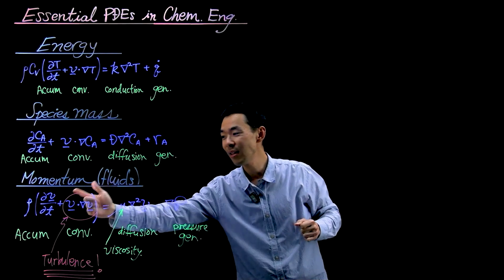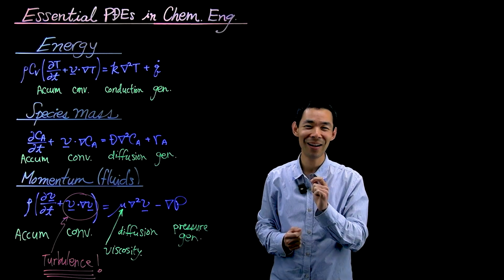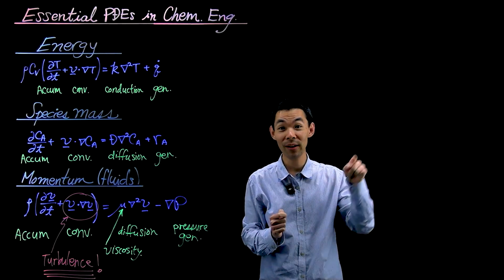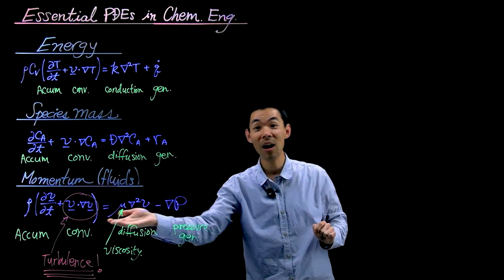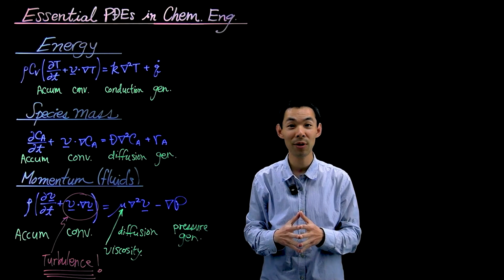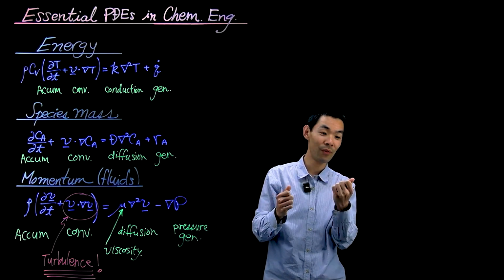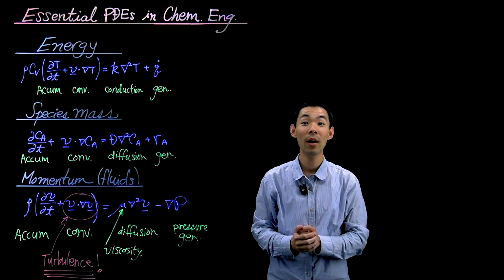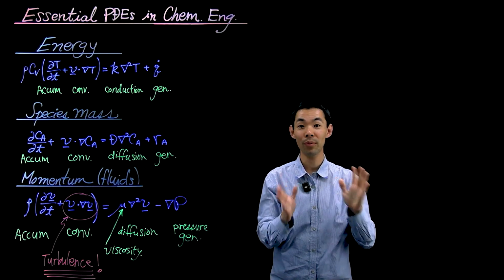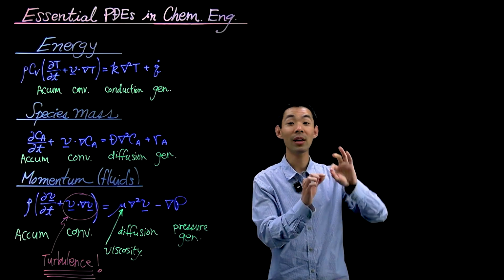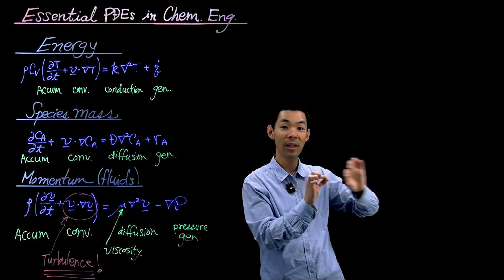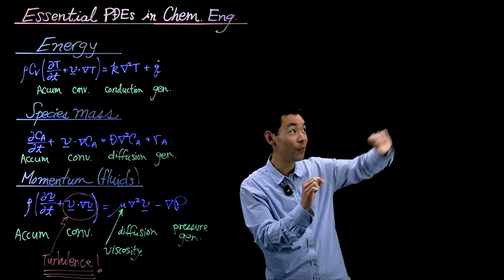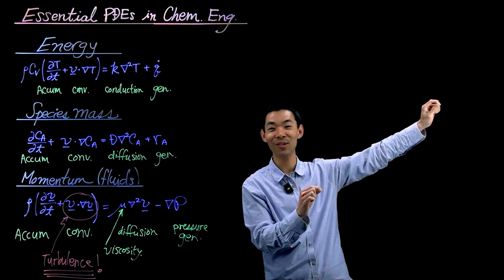But when you have a nonlinear term, which now you guys know how to identify nonlinear terms because this is the function you want, v, multiplied against the gradient of itself, so that's a parabolic quadratic term, and therefore this is a nonlinearity in the partial differential equation. And nonlinearity means you put up an input of one thing and it becomes turbulent and chaotic and you can't predict where that particle will go as a function of time. It's chaos, complete chaos. Chaos in the mathematical sense. You cannot predict where that trajectory will go as a function of time. And small little minor deviations in your initial condition will result in very, very drastically different outcomes in trajectory space.